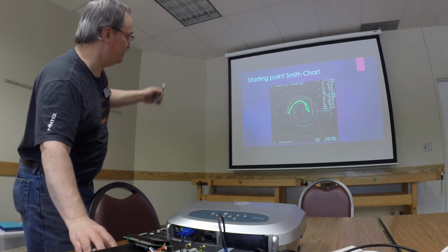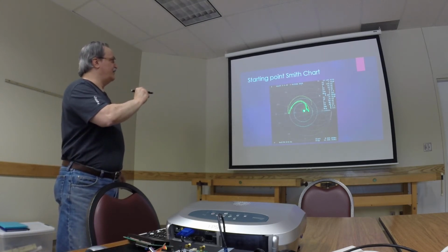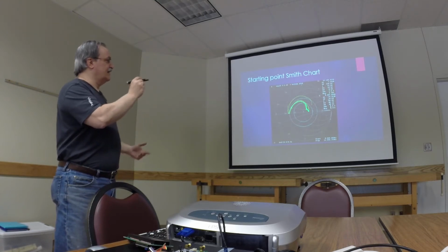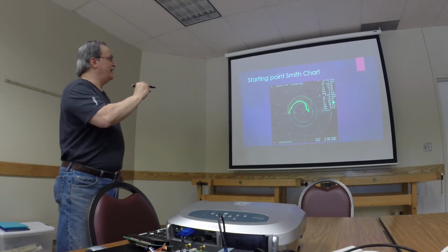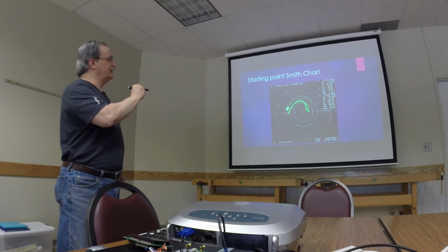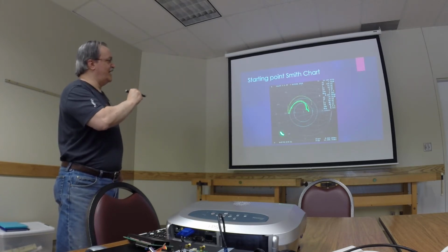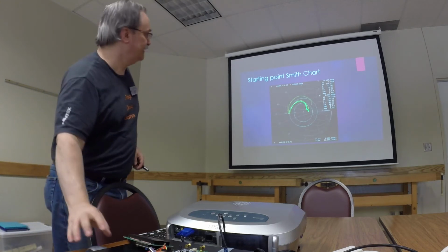Anyway, when I plotted this out, and it's an eye test already as it stands, I'm going from a best case VSWR of, in this case, 2.6, so I was cutting the antenna and whatnot, and then at 9.4 megahertz, I was down at 1.4, and at about 63 ohms with 12.2 reactive, which is all inductive on the top of the Smith chart, all capacitive down here. And for wire antennas, you can expect them to traverse the Smith chart in the upper half because they're going to tend to be inductive.